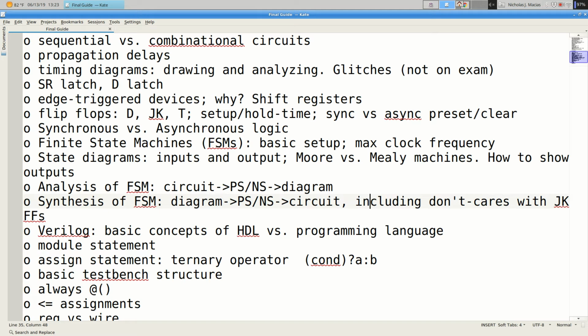Wires and registers, okay? Wires for something that we're going to use an assign statement for, probably. Registers for something that needs to remember a value, which usually means it's something that's inside an always block. Because in always blocks, we don't say assign, we say this thing, arrow, that thing. And it says at this clock edge, we want to copy this into this other thing. If you copy into a register, it'll remember it, right?